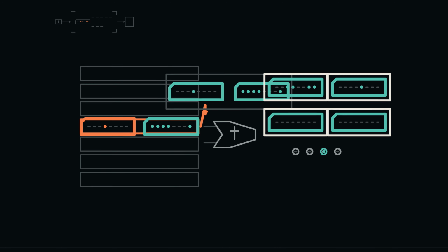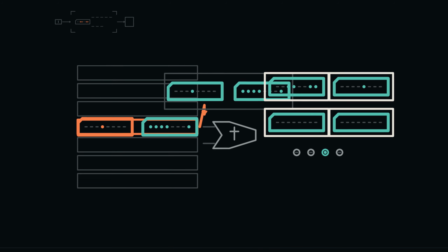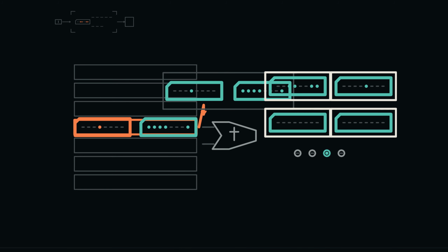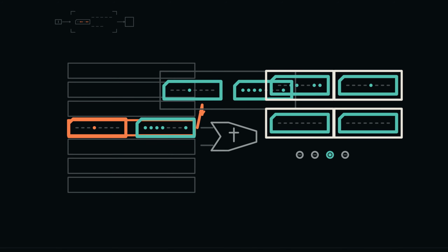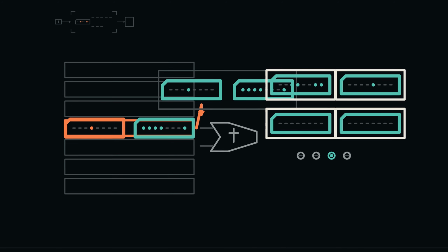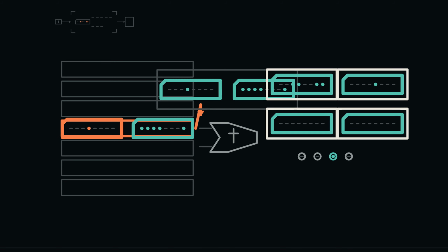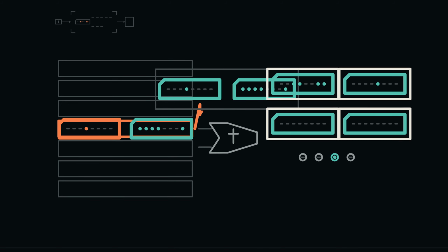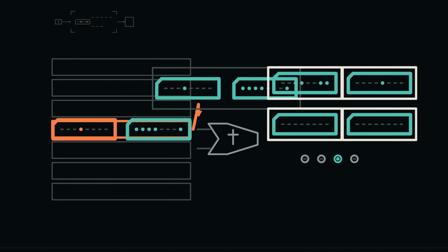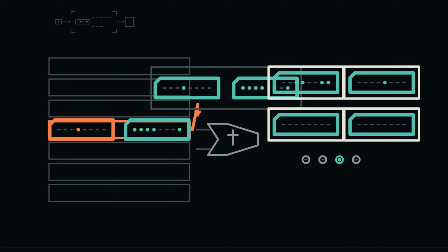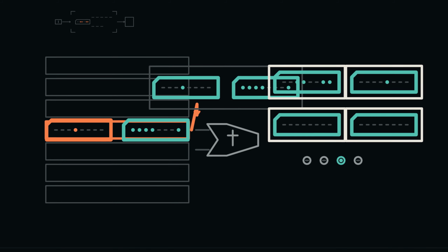The first polling loop belongs only to the key press for 3. Before that event arrives, a status load returns 0. Compare sets the 0 flag, and branch returns the program counter to the start of this loop. At cycle 25, the input adapter places hexadecimal 33 in the queue. The repeated status load now returns 1, so the branch falls through. A data load consumes that 1 byte.